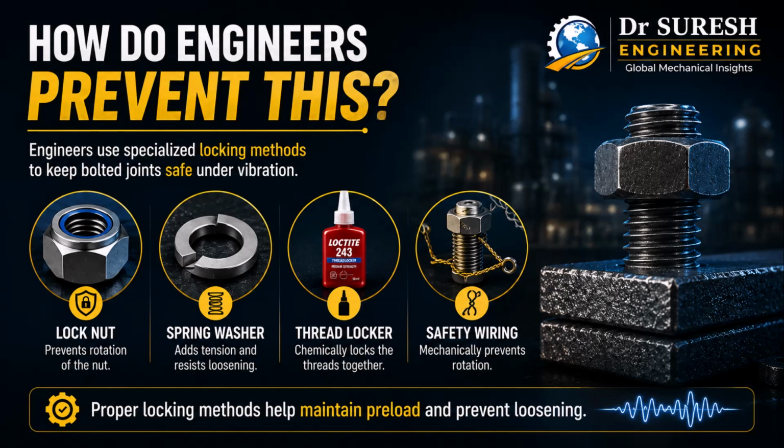One common solution is the lock nut, which increases resistance against rotation. Spring washers help maintain tension and reduce the effects of vibration. Thread locking adhesives chemically lock the threads together, reducing microslip between the contact surfaces. And in critical applications, such as aerospace and high-speed machinery, engineers even use safety wiring to physically prevent nut rotation. The goal is simple: maintain preload, preserve clamping force, and keep the joint safe under dynamic conditions. Because in engineering, proper locking methods prevent failure.